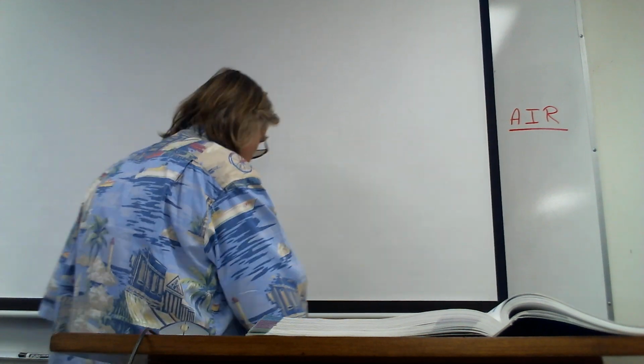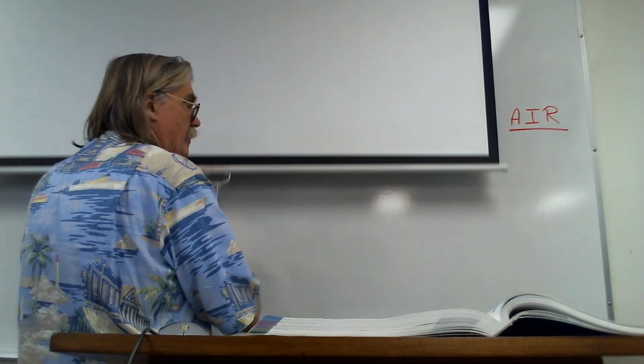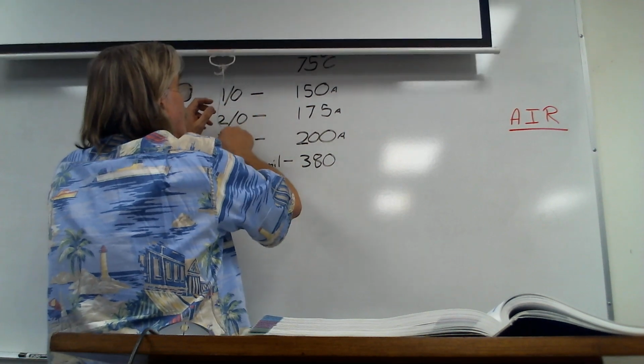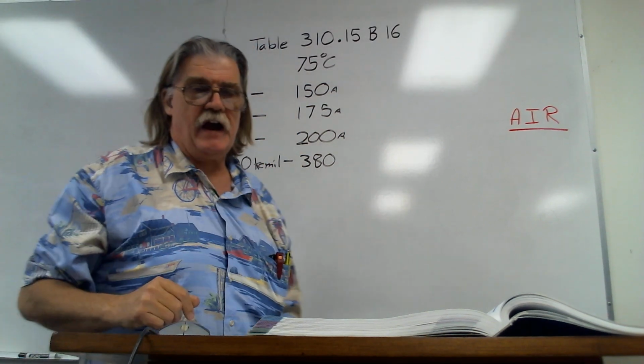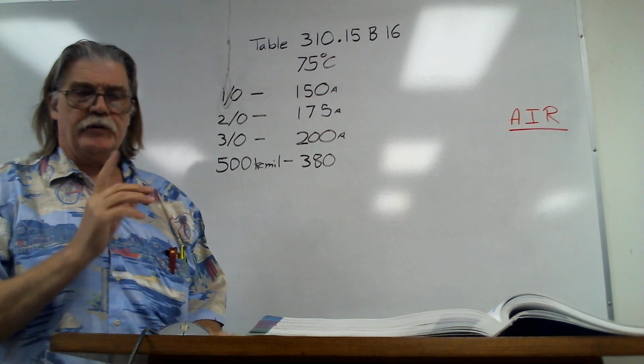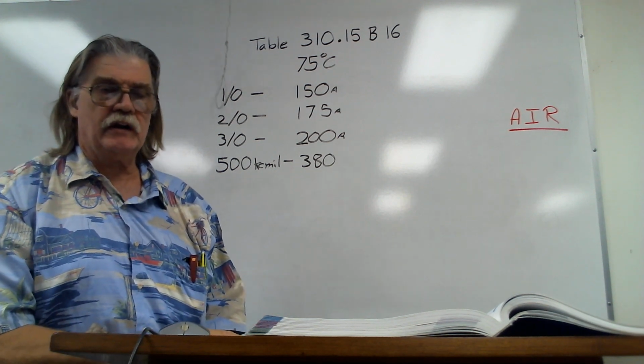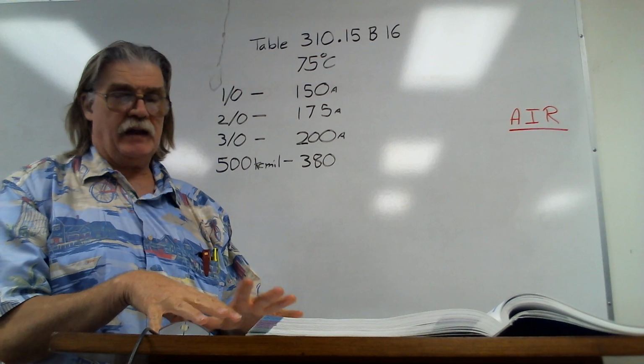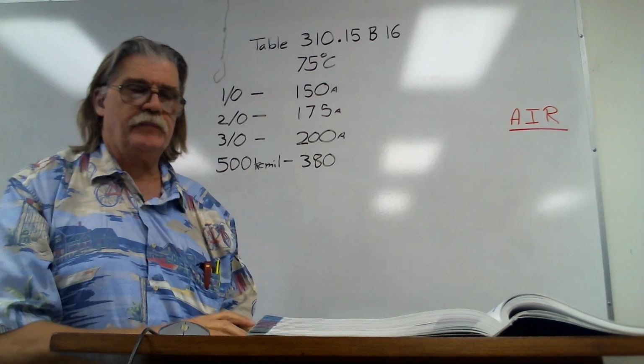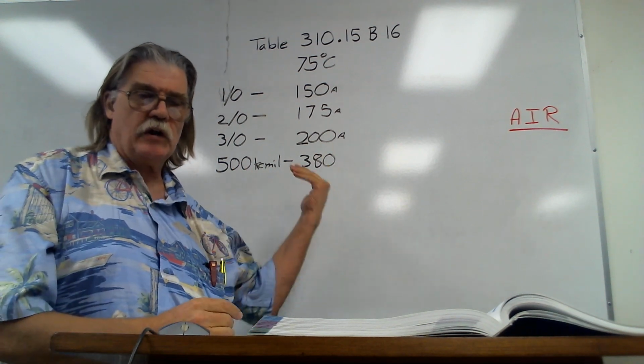The second thing, the ampacity of the conductors does not correspond with the standard ampere rating of a fuse or a circuit breaker without overload trip adjustments above its rating. Right? So, what does that mean? Well, let me pop this up here for a moment. I put some values from Table 310.15(B)(16) on the board here because I tried to put the page up there and the camera just wouldn't focus. So I wrote them down for you right here.